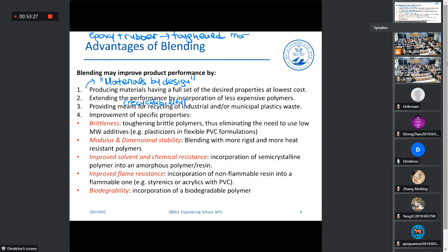So the epoxy stress strain curve generally looks like that, okay? But when we include the rubber in there, we can have a material that looks like that, okay? So it can elongate more. Of course, the presence of rubber reduces a bit the ultimate strength or the modulus, but generally we have higher toughness. Toughness is the area under the stress strain curve, okay?